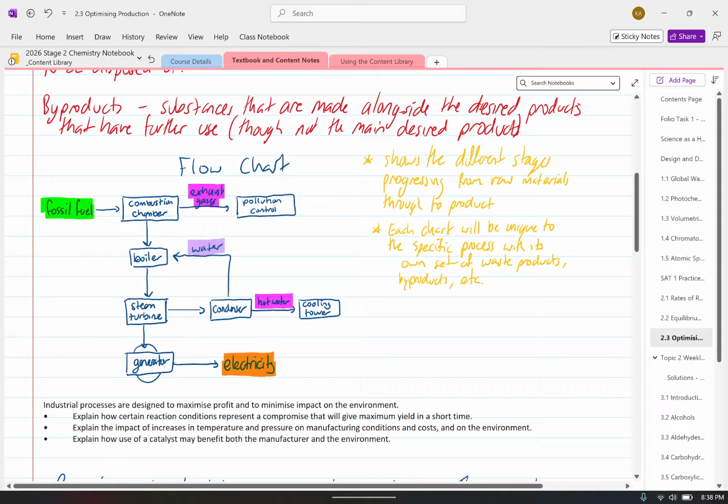So this steam, the water from the steam turbine, has to condense in the condenser. It has to turn back into a liquid. That water is a byproduct which can go back into the boiler as liquid water, which can then be heated up by further fossil fuel combustion reactions. Now, as it's condensing, it's going to lose heat, and we use this in the condenser. It does this using what's called a heat exchanger. So you cool this water down, but you have to transfer that heat somewhere.